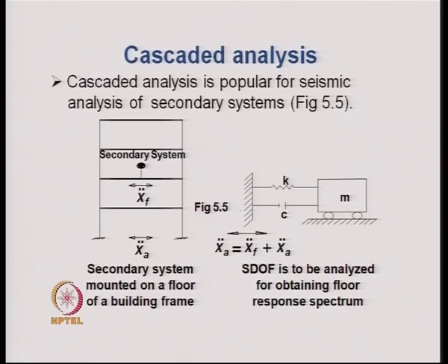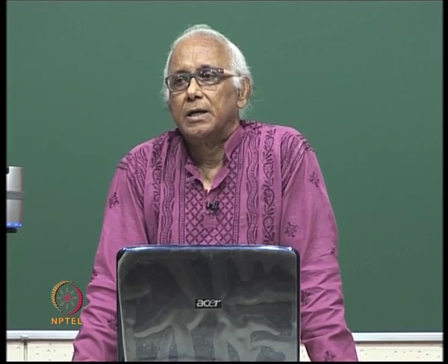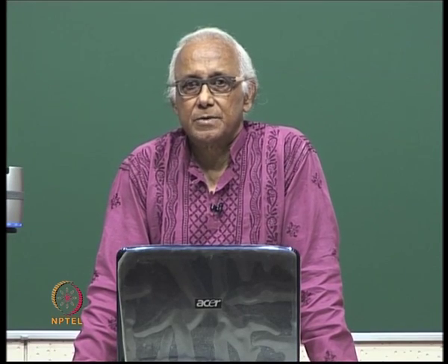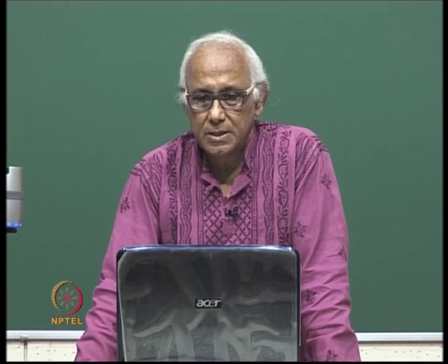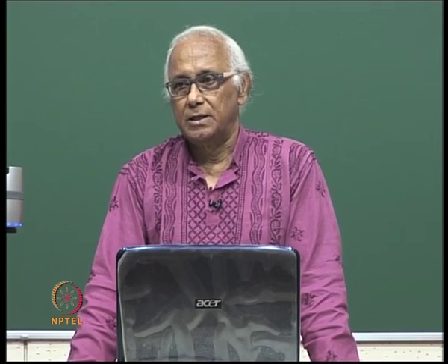Secondly, the cascaded analysis is performed because in cases where you have secondary systems along with the primary system, the damping matrix becomes non-classically damped.